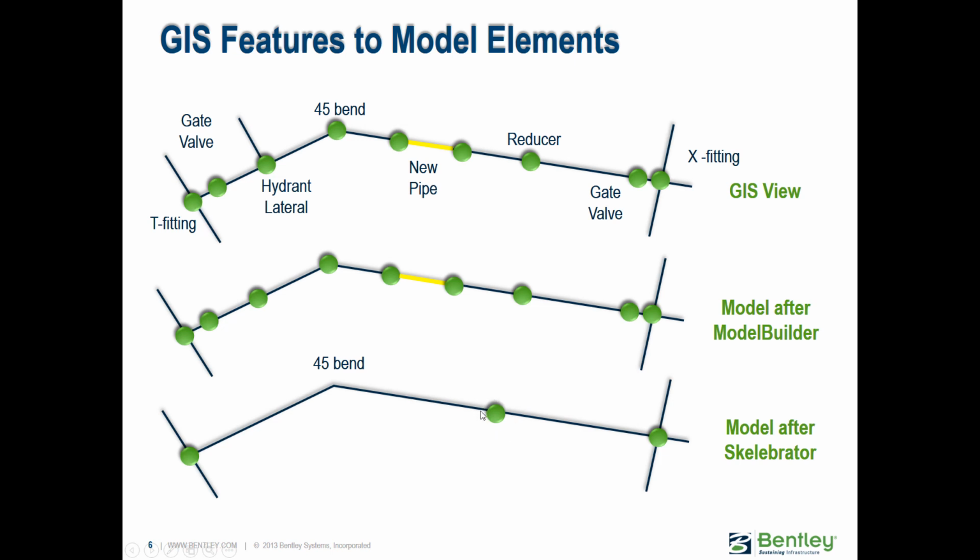And maybe this junction right here might represent a high point. So it's something you'll want to look at first, instead of just importing the entire model and then running Skelebrator on the entire model without doing any preparation. That's where you could accidentally remove some of those high points or significant areas. So it does take a little bit of preparation time, kind of understanding the system after it's been imported and cleaned up before you actually go and fully skeletonize it.